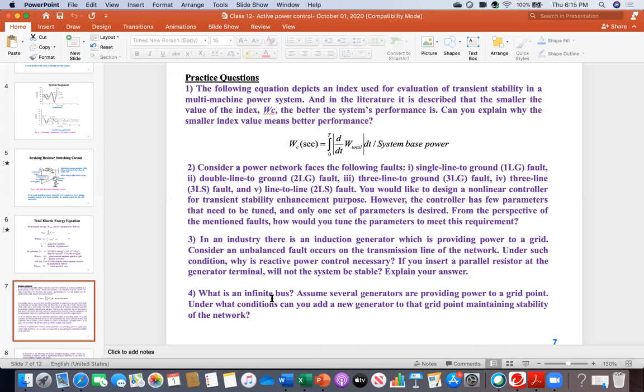When you analyze a power network, to calculate the power flow, to calculate active and reactive power, you have to consider one of the buses in the system as the infinite bus, meaning that is your reference point. Reference means fixed. That's why the voltage and frequency will not be changed, of course, within a certain limit. So infinite bus, in other words, a reference bus, a slack bus.